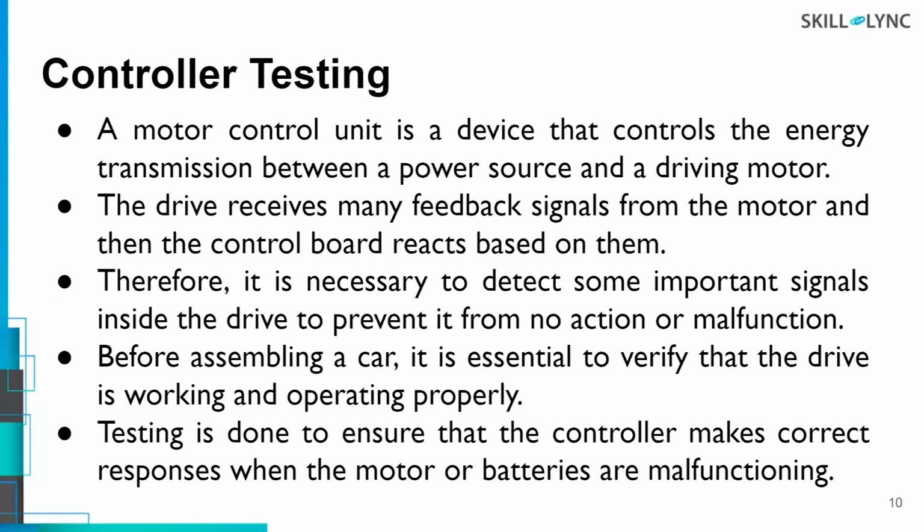Okay, so what acceleration is expected, and whether the controller is giving the duty ratio according to that, so that you increase your voltage and your velocity increases. Again, that feedback comes to the controller that the speed has increased and the accelerator pedal is no longer pressed. So you can just keep the control action in a constant manner. And that kind of thing is ensured by controller testing.